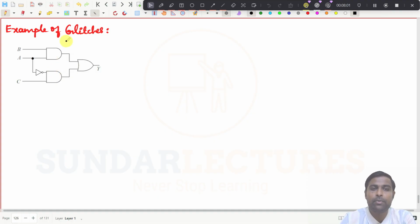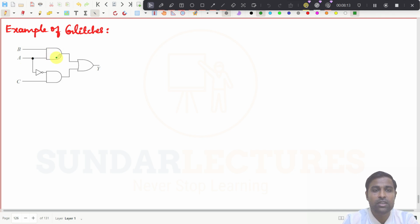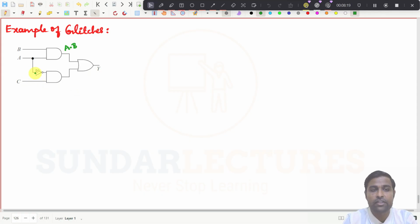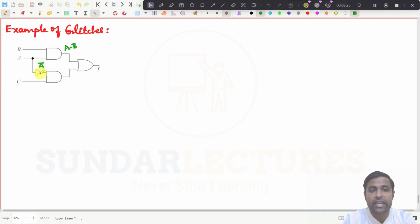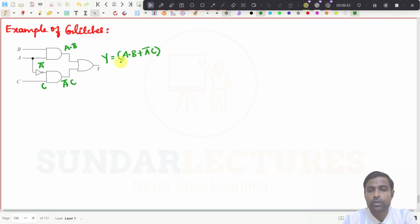So that is what we are going to see here. We will take an example of how a glitch occurs in a logic circuit. For example, we consider this to be a logic circuit. This is an AND gate. So what is the output we will get here? This will be A dot B, right? And here this input will be A bar, because this is A, so the NOT gate will make A into A bar, and this is C. So what you will get here is A bar C. And the output Y will be equal to A dot B plus A bar C. So this is the output of this particular logic circuit.